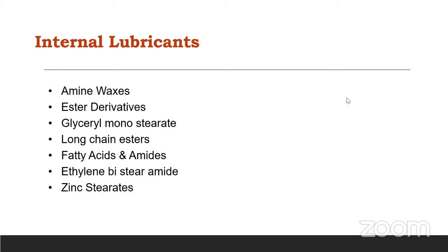Okay, and just like you told us that external lubricants are also there. Let's say if I am facing an issue of material sticking, there are some kind of materials which may react with the external lubricants. So in that case, to avoid the sticking of the material with the metal surface of the cavity, can I use internal lubricants in place of external lubricants?